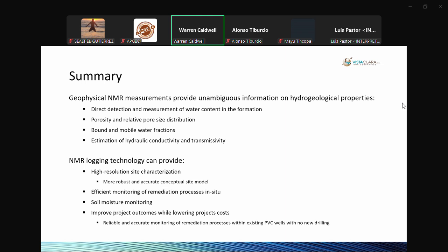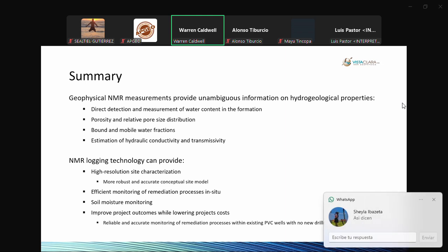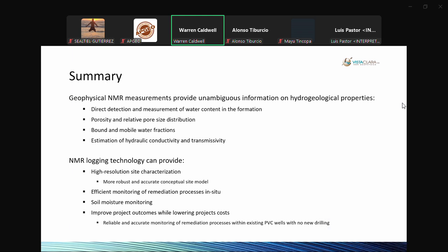Any instrumentation that's installed, for example, in the annular space of a well, if the sensors are metal or there's copper wiring, that can impact the NMR tool negatively by introducing noise, or if there's sufficient quantities of metal, it can potentially damage the electronics in the probe.